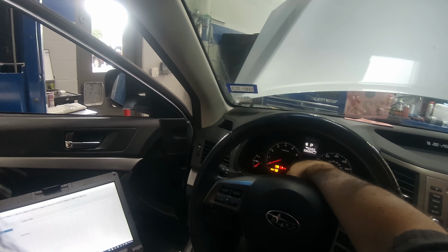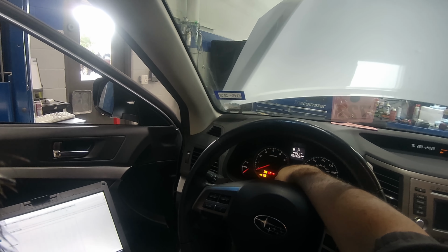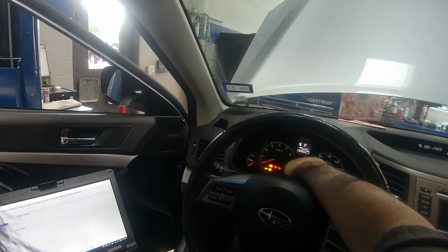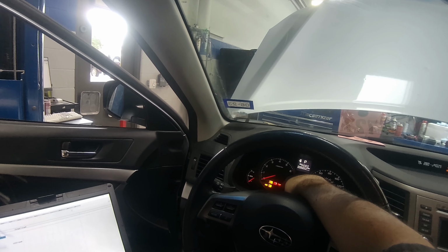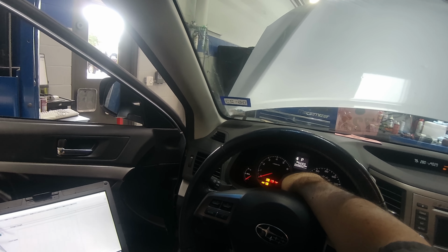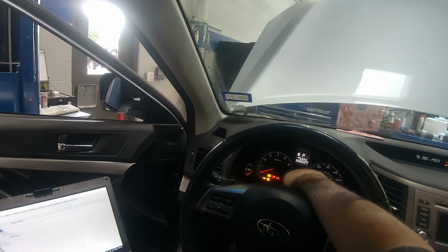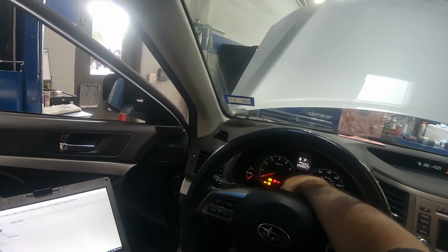If the oil pressure switch is activated, meaning there's no oil pressure, like right now, there's a ground being provided to that light. When I turn the vehicle on, the oil pressure will push open the switch and it'll take away the ground from that light and turn that light off. That's what turns that light on.